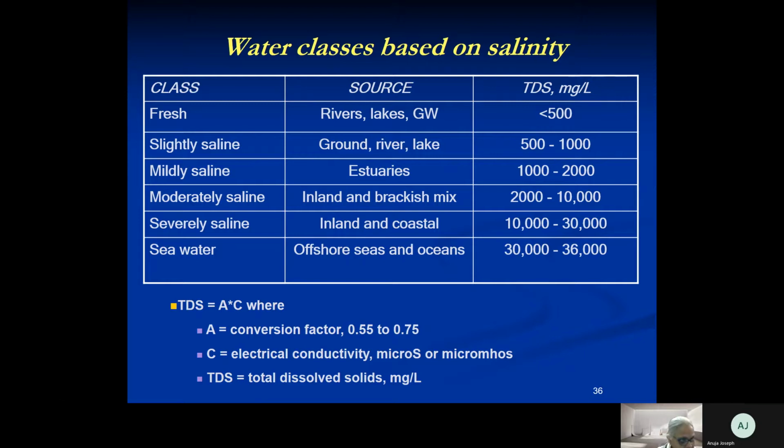So there is a shortcut, and the shortcut is electrical conductivity. These days we have portable electrical conductivity probes. They are just the size of your digital thermometers. They even look like your digital thermometers. So you get a readout, just like you have your temperature readout, you get an electrical conductivity readout. And once you know the conversion factor, you do the TDS a few times in the lab, and the remaining time you do it on the site itself. You take your electrical conductivity probe. It's a pocket sized probe. You go anywhere, dip it in water.